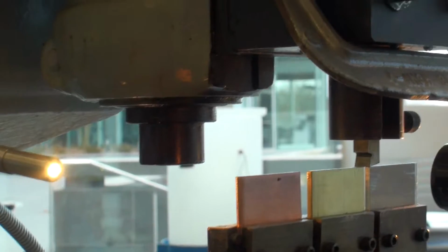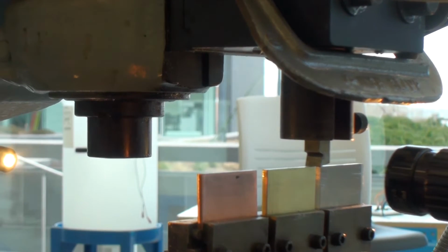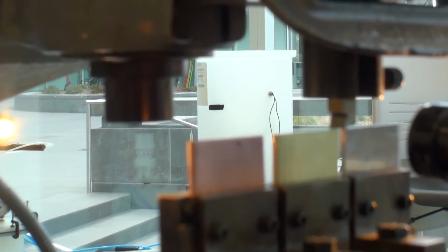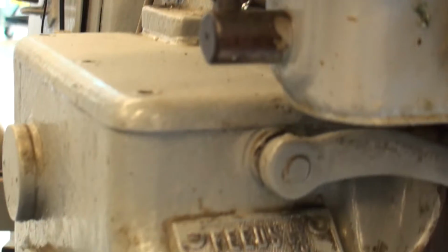Cut. I'm going to speak first, so don't hit any buttons yet. Now we are going to do our brass piece of material. Okay, so it's at the same feed rate, so 0.6, and again we just go. Again, as you see, it's moving extremely slowly. The camera fools you into thinking it's moving faster than it actually is. But yes, so we're just going to record that. So same thing as with the aluminium.